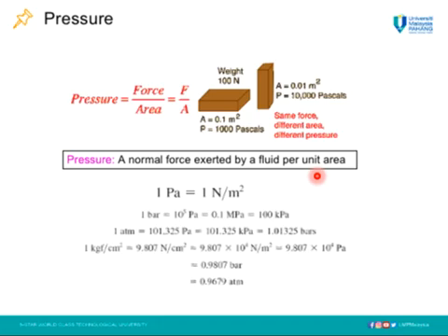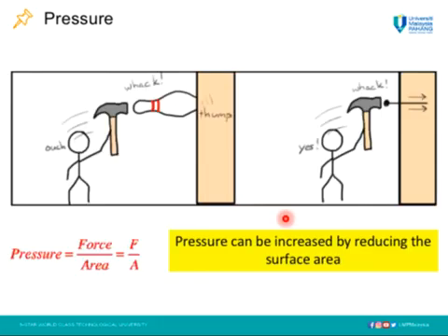Pressure is always used on solid surfaces, which is similar to normal stress, or the force acting perpendicular to the surface per unit area. Since pressure is defined as force per unit area, the unit is newtons per square meter. It is also known as Pascal. The pressure unit Pascal is too small for most pressure measurement. Therefore, we always use megapascals or kilopascals. Bar, standard atmosphere, and kilogram force per square centimeter are the other pressure units that are commonly used in practice.